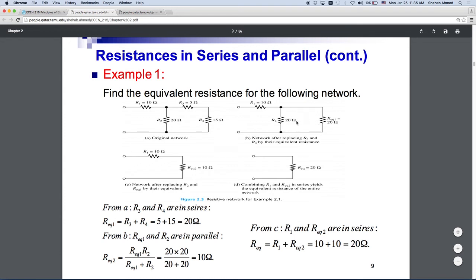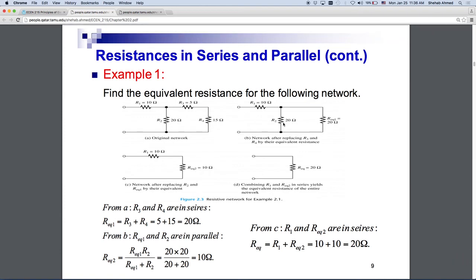So now if they are different values, I don't care, right? This is 1 ohm, 10 ohm, this does not really matter. I know that the voltage across them is 10 volts. And you're given their impedances from your R equivalent calculation. So this is 10 volts divided by 1 ohm, so this is 10 amps. And the other branch is 10 ohms, so 10 volts divided by 10 ohms in that case will be 1 amp. So one branch will have 10 amps, one branch will have 1 amp.